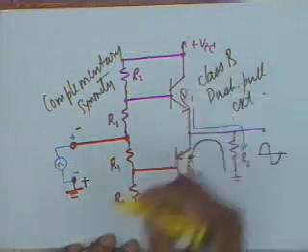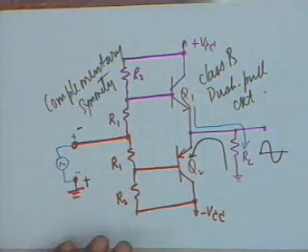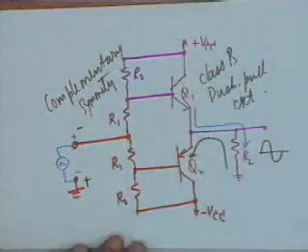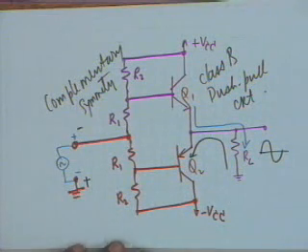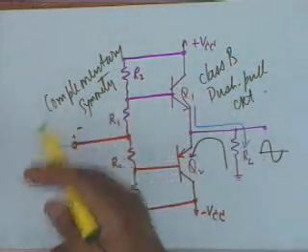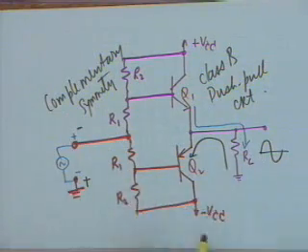The complementary symmetry required, you wanted to avoid transformers, right? And therefore, the collectors have now been declared as dead. They are connected to ground. You take the output across the emitter, and this is why I had to introduce the emitter follower circuit. All right. This, as I said, is the most popular circuit.